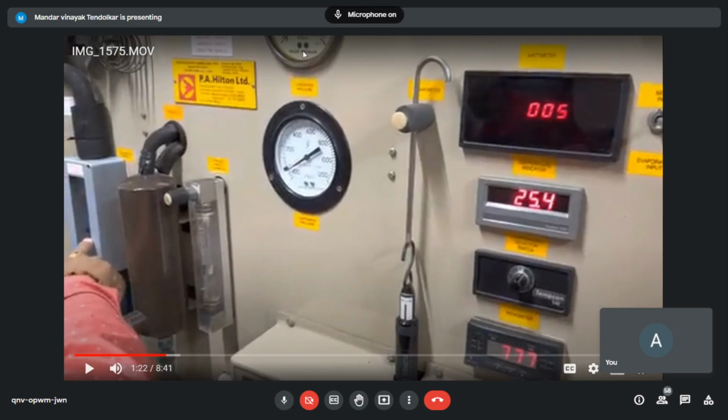Fine with this. Pressure just now I have explained. This is somewhat negative, maybe minus 25 kPa. This is gauge, not absolute. And over there somewhat 150, 160, whatever it was. So 160 kPa condenser side, minus 25 kPa evaporator side. That much is your pressure ratio.